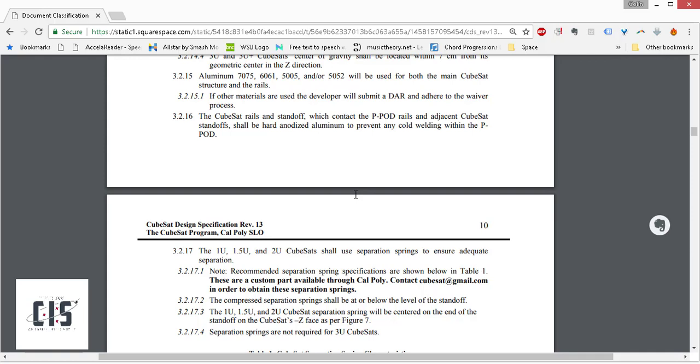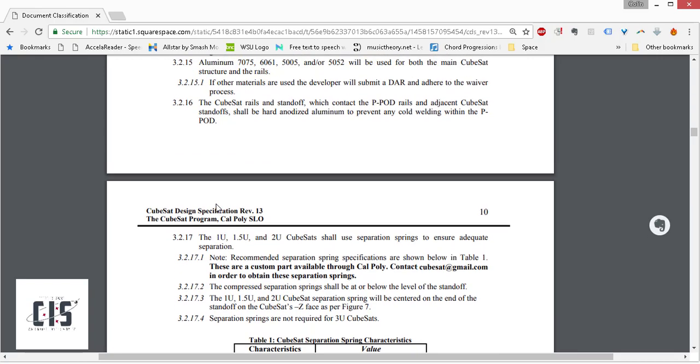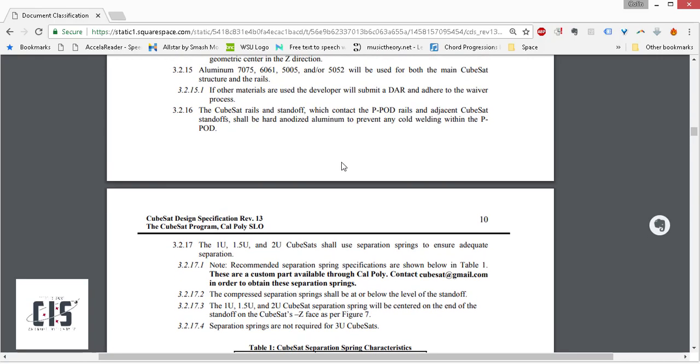Yeah. So the anodized, does that look hard anodized? It appears to be. It's black. The black stuff tends to be hard anodized. You can get other colors like blues and reds, which are really pretty, but they're not hard anodized. So if you're on McMaster-Carr, or wherever you're ordering your aluminum, and you get the black anodized stuff, probably good. Just make sure the material is also tempered properly.